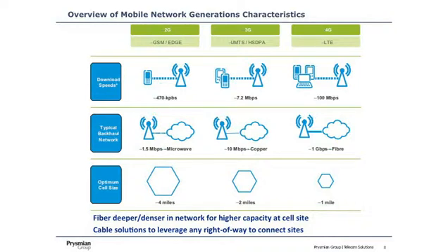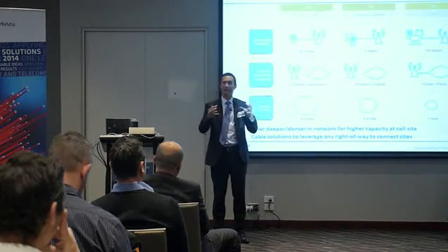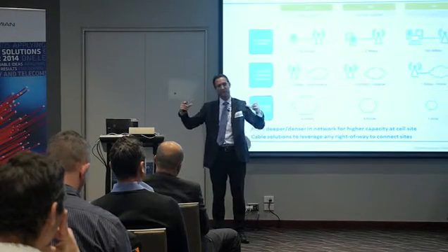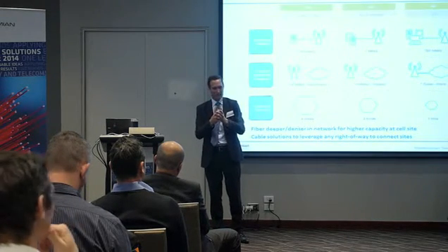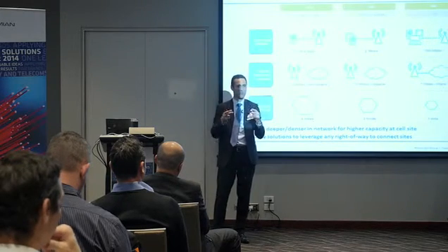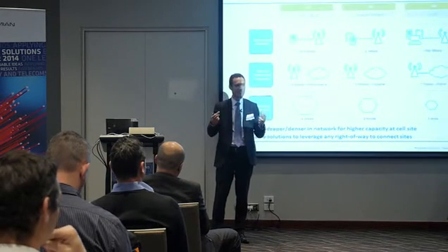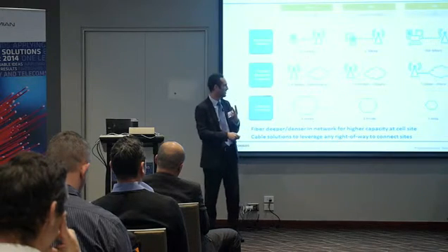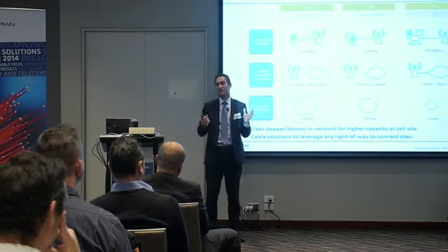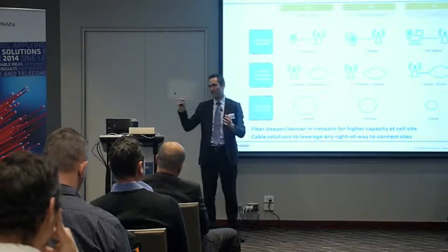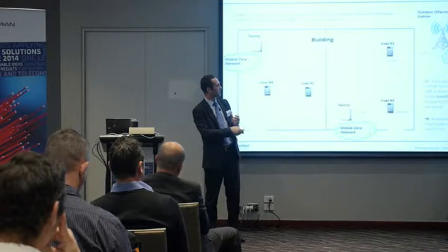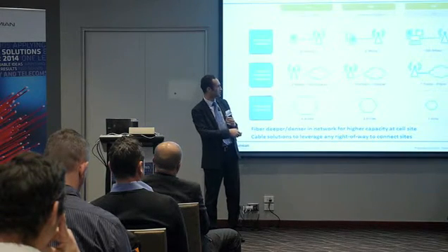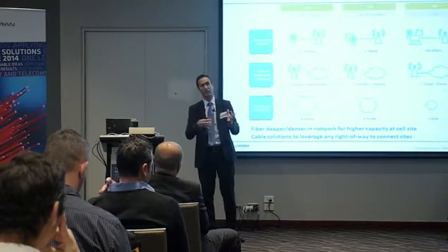Again, the coverage, because the more complex the modulation format that is used, the higher bandwidth you need to convey, the smaller the coverage. But the network operator cannot live with that. They just need to propose bandwidth to all on all the coverage. They need both. So what do they have to do? Increase the number of cell sites. So make smaller cells and really increase the density. Increase the density and with a lot of connectivity, which is, conclusion, fiber all over the place.